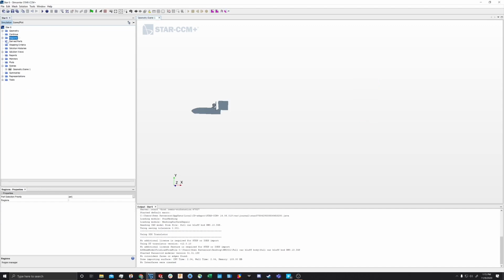And then the next step that we're going to take is to create some continua. The first continuum we're going to make is the mesh continuum. As you will learn in your aerospace courses, for a lot of these fluid analyses, the way you do it is with a control surface and a control volume. And the mesh breaks your big region, that box, and your parts, your bodies, into millions of small control surfaces and control volumes through which it'll do its computations.